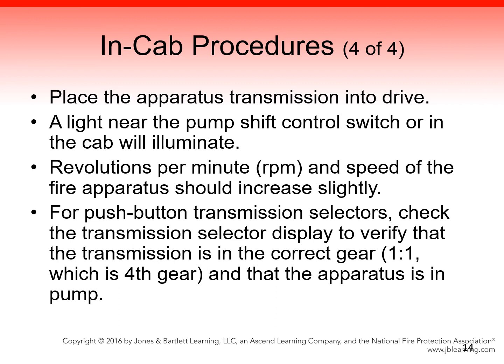For push-button transmission selectors, check the transmission selector display to verify that the transmission is in the correct gear and that the apparatus is in fact in pump. Seeing 5 on the selector would indicate that the shift from road to pump did not occur and the apparatus is still in drive. These changes signal that the transmission is now spinning the impeller of the pump.